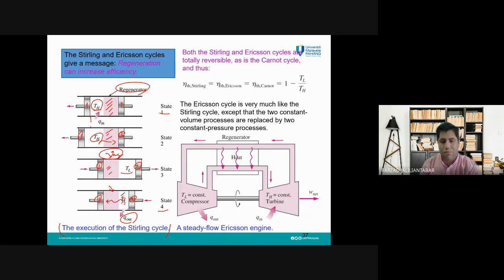So, when we have Q out here and we have a compression here, the temperature remains constant, TL. But when it travels through this substance, its temperature will increase again. Why? Because we have a hot regenerator or substance here. This cycle will continue, and we can have a Stirling cycle by using this regenerator. Without this regenerator, it doesn't work.